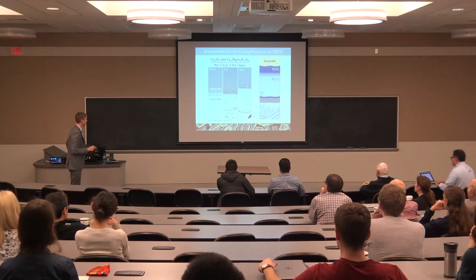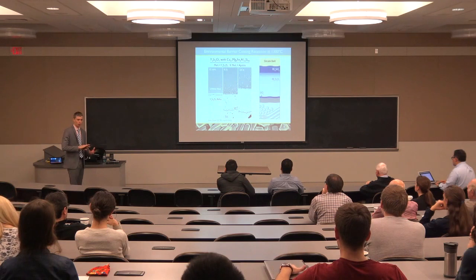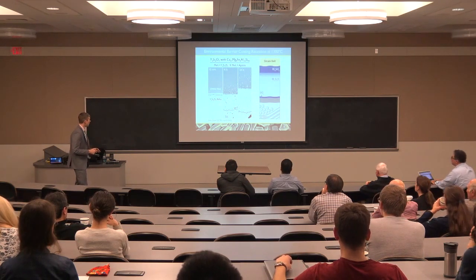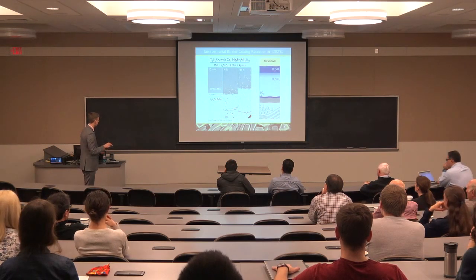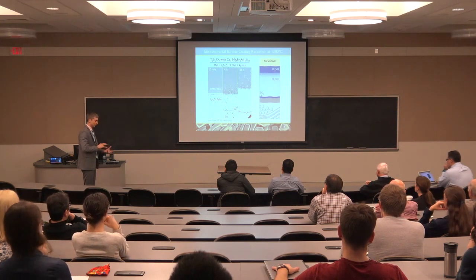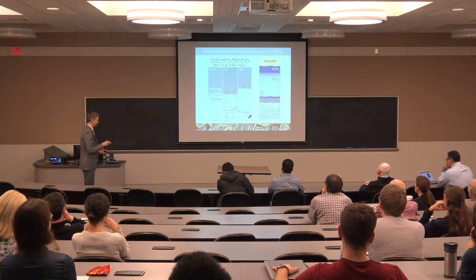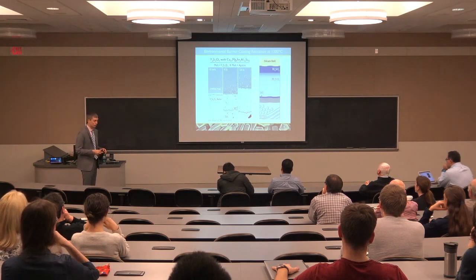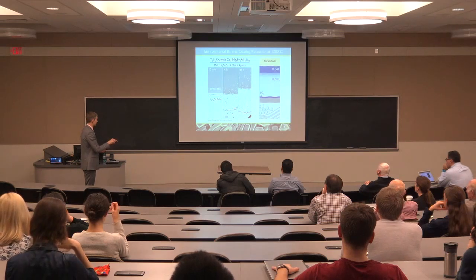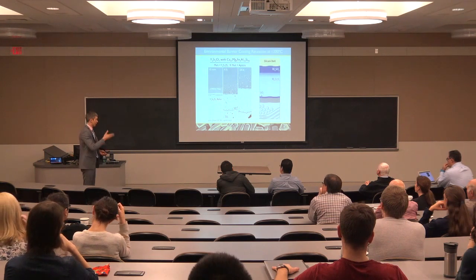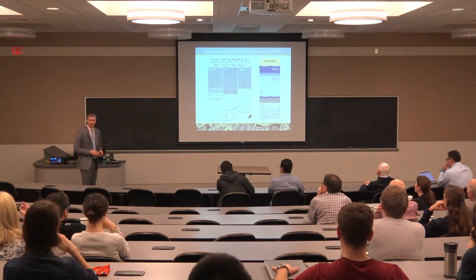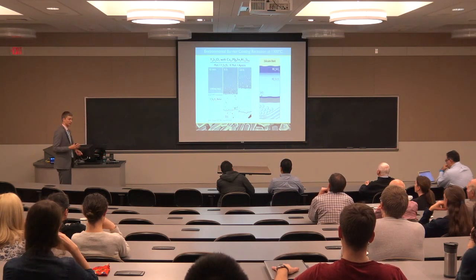We switch now very briefly to the environmental barrier coatings, where we remember that we want the opposite behavior. We want very little interaction. What we find actually happens, if this is a big pool of this deposit on the surface of a coating, is that progressively, in just a matter of minutes or hours, the coating is converted to a mix of liquid plus apatite. And the apatite has a CTE that isn't as well matched with the substrate, and so as the thickness of this apatite plus liquid layer grows, the thermal stresses upon cooling grow, and eventually you get cracks in the coating that bifurcate and end up in the underlying structural material and cause pretty significant issues in terms of the long-term durability.